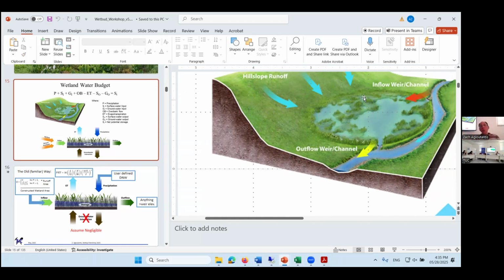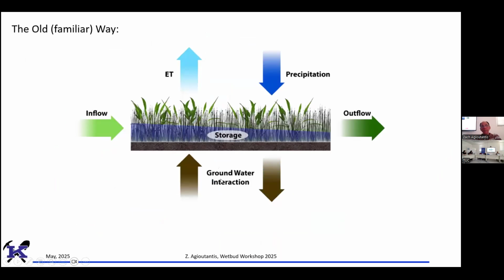Now, when you construct the wetland, you can actually specify how thick your soil layers are going to be and what soil you're going to put there. The basic model cannot utilize that information. The basic model only uses an average permeability K value for the whole wetland bottom. The advanced model, however, you can specify layers. You can say this layer is 15 centimeters high, and this is another 15, and so on. Okay, good question. Any other questions? Okay. Let me go back to this.